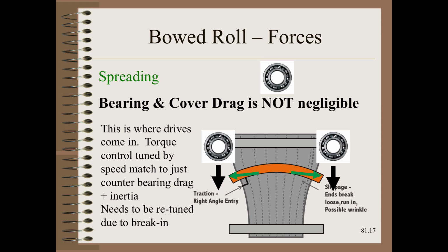This ideal measured torque control is very different from common drive practice, in which either speed is matched closely at one or two speeds, or speed droop is enabled in the drive to prevent the drive from going into an overload condition.